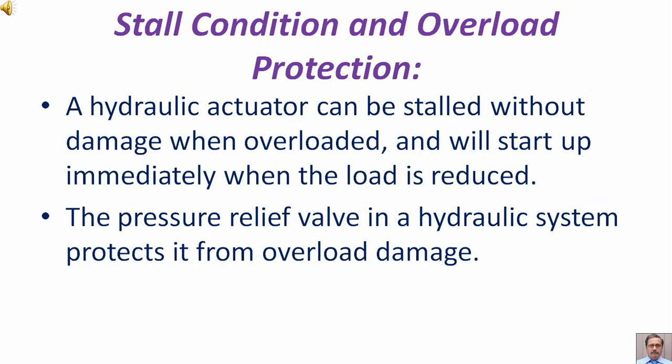Stall condition and overload protection. A hydraulic actuator can be stalled without damage when overloaded and will start up immediately when the load is reduced. The pressure relief valve in a hydraulic system protects it from overload damage.